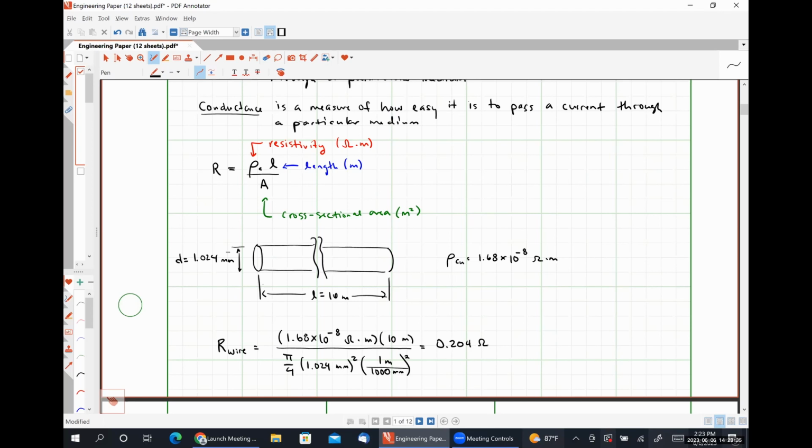If you run it at a lower voltage, it can actually cause damage to the compressor motor over time. But other than things like that, where you have things that are consuming large amounts of power because they draw large currents, the resistance of the wires is fairly inconsequential.